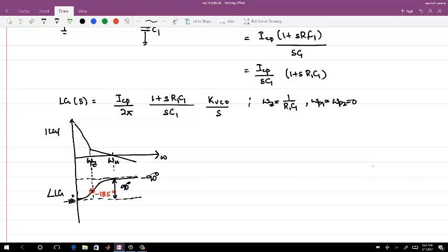The additional integrator which we put is to get a certain control voltage which is proportional to the frequency error information. I have just introduced the proportional path right now from the stability point of view.